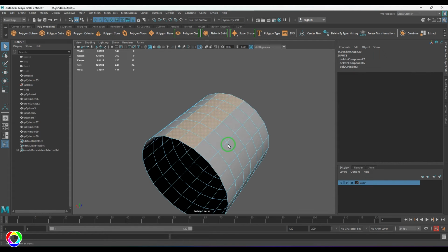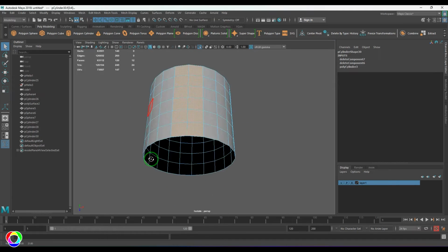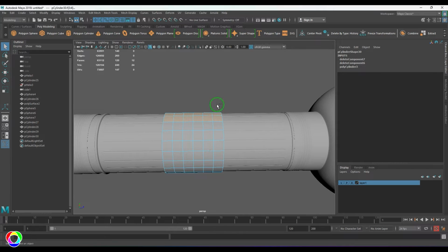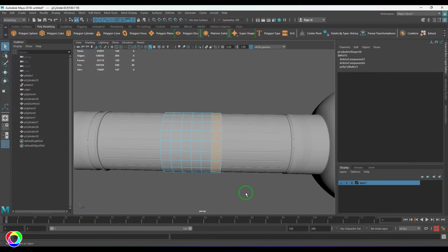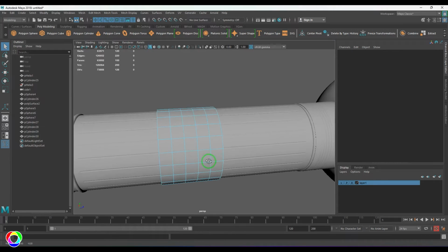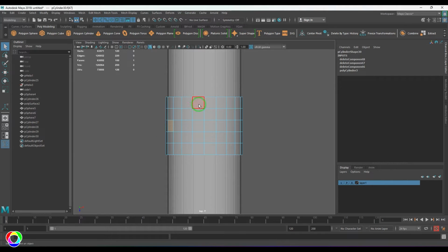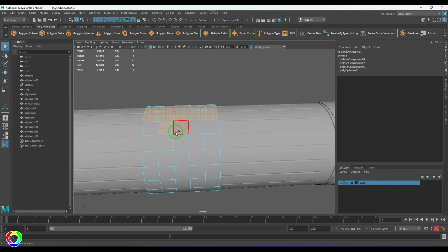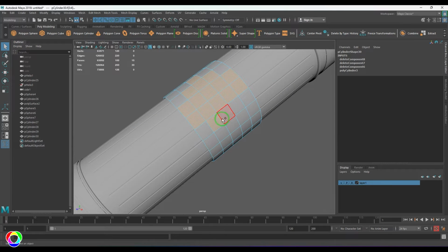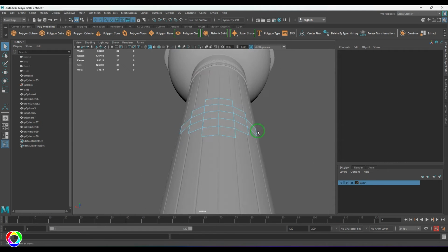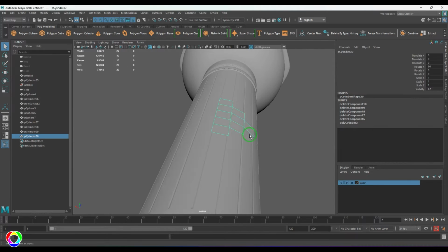Okay, so I have these two set of faces which I'm going to use for the switch. Let me see for the thickness part. Yeah, that should be fine. Okay, let me delete this up to this one. Okay, now I'm going to select 3 faces here and 1 face there, and rest of them I'm going to delete from there. Okay, maybe I can delete 1/2 of that and model the symmetry.